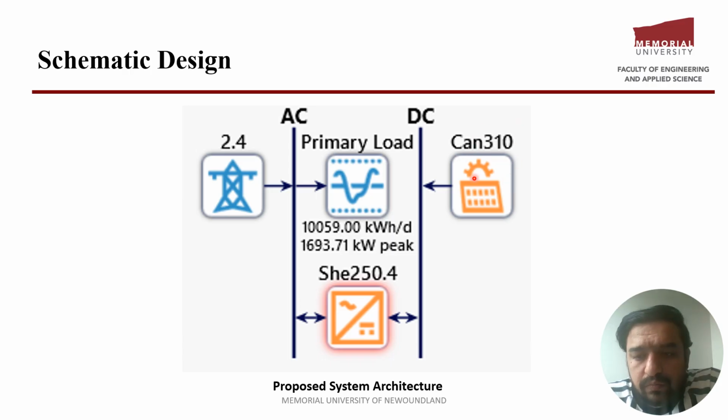Canadian Solar CS6X-310 is the PV module employed in this work. It is a 60-cell monocrystalline module with 310 watt maximum output. This makes the PV module suitable for direct grid connection. The solar PV's output DC voltage must be converted into AC to feed the building's load. The Shenzhen BYD BSJ 250K model power converter is used in HOMER to perform this function.